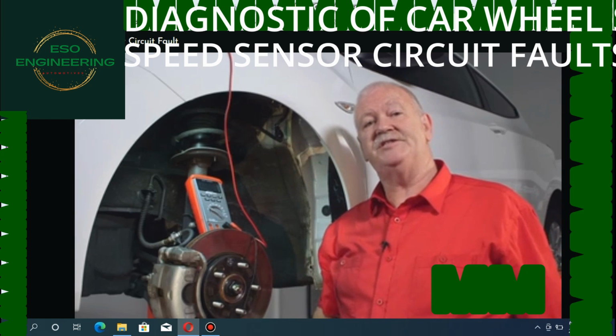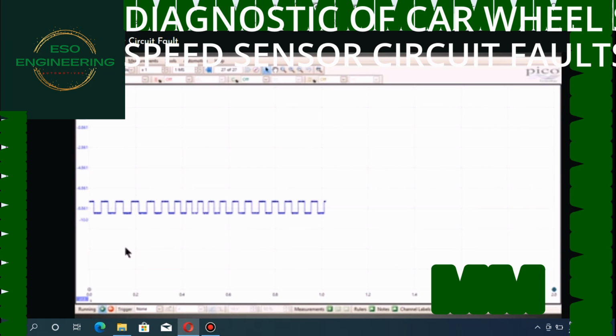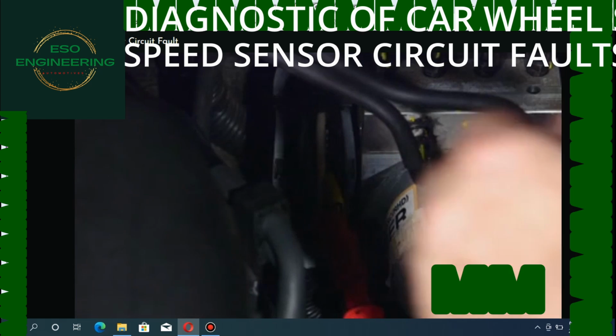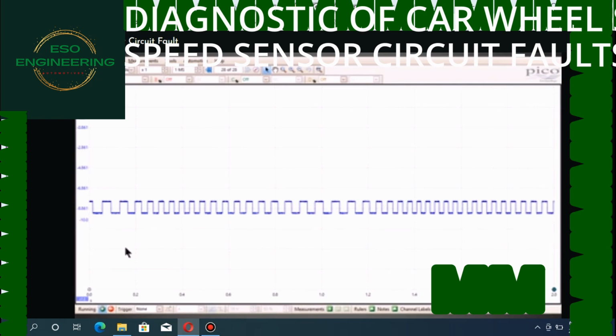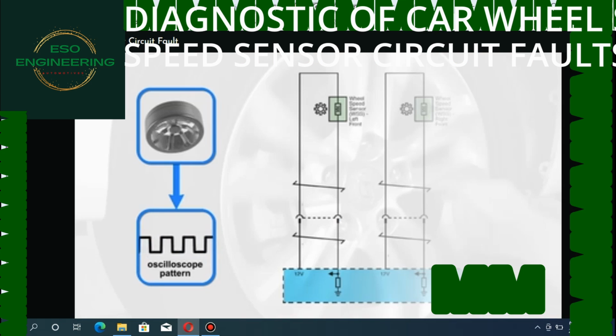So it'll be necessary to test the sensor. To test the sensor, you'll need a graphing scan tool or an oscilloscope. If using an oscilloscope, it will be necessary to backprobe the module or the sensor to get a pattern. Again, turn the wheel at a constant speed while observing the pattern. You should see a steady square wave. If these tests reveal a good pattern, then the fault would have to be the module.